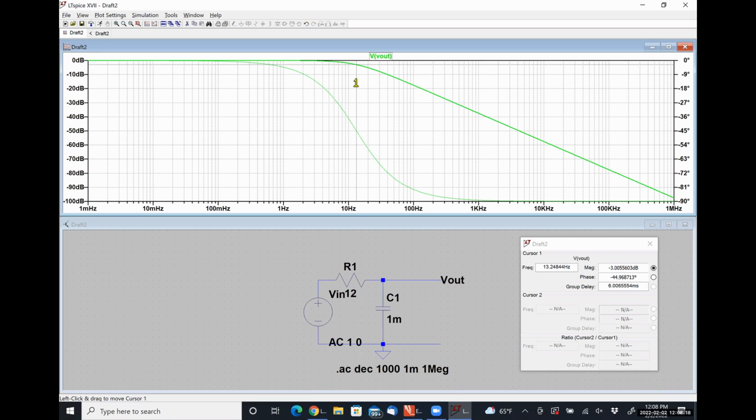So why isn't this number 83.333? Student: The frequency should be angular. Exactly right. Omega that we determined is an angular frequency, which should be exactly 2 pi times larger than this value. So if we divide that 83.333 by 2 pi, we get 13.263, which is pretty dang close.